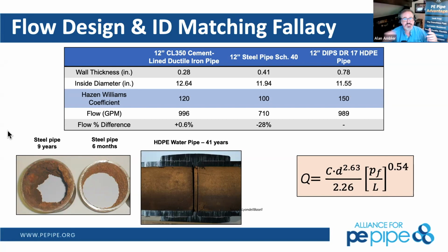Velocities may increase through a section if that ID is smaller, since we're achieving a higher pressure rating through the HDPE itself, but then the velocity will increase there. The absence of lots of fittings, from 22 degree and under bends that have to be inserted into a bell and spigot system, is saving us massive friction factor through a complicated network.